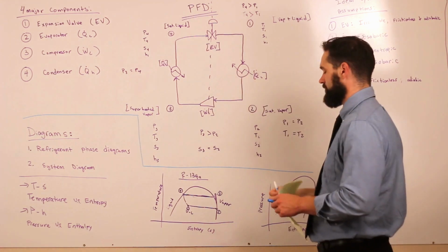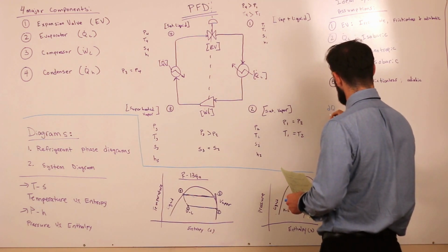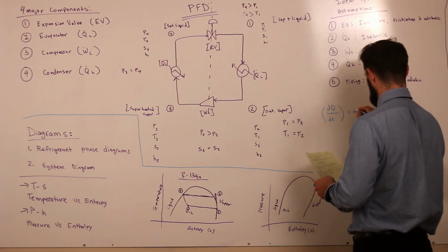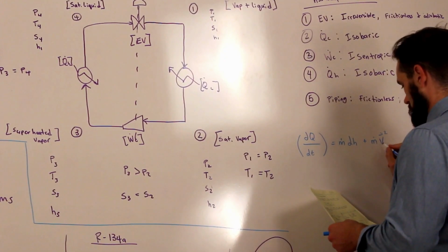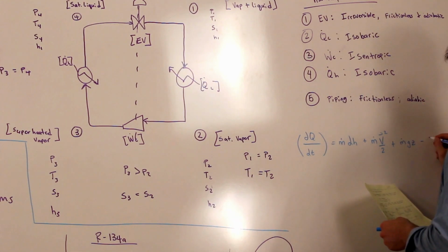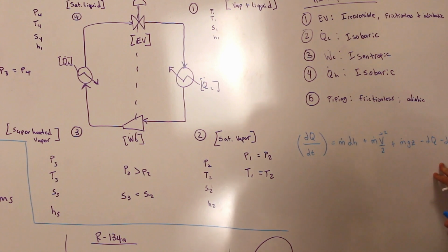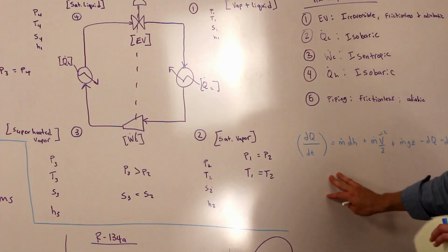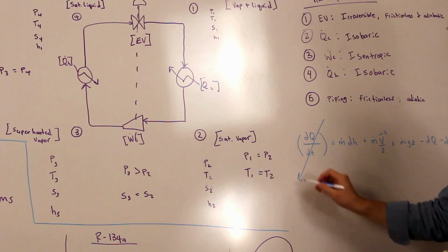Before we start drawing our system boundaries here, I want to write out the equation for the energy balance equation. I'm going to write it out and then I'll explain what each piece is. So here's our generic energy balance equation. Over here what we have is the accumulation of energy per unit time. In most, at least lower level classes in chemical engineering, you always assume steady state. So what winds up happening to this term a lot of times is we assume that it's zero.